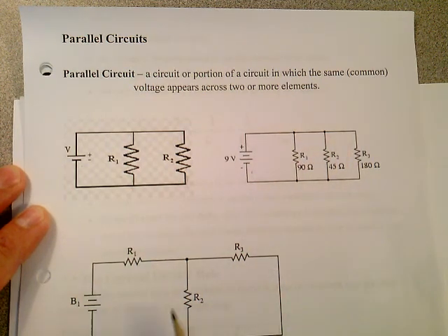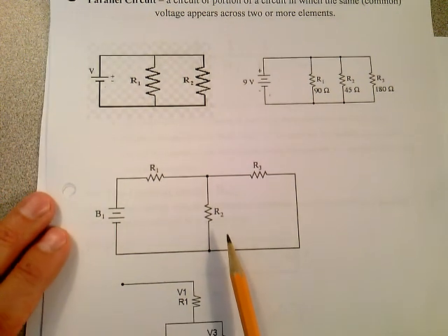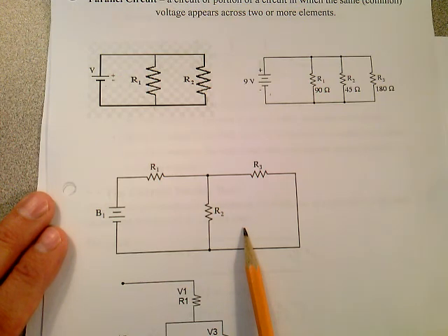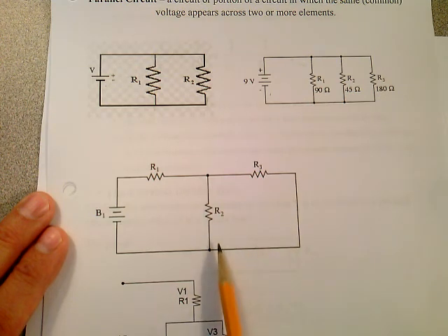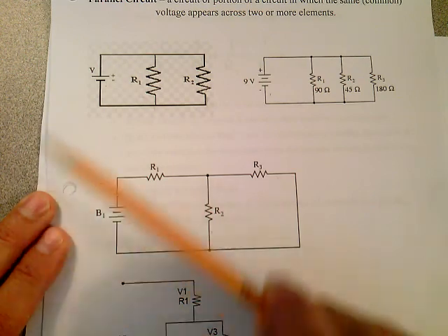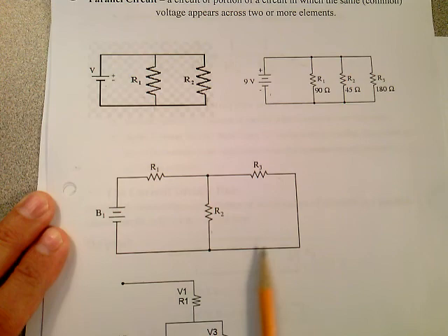Here's another example, but this is an example of a series parallel circuit. Take a look at this circuit. Do you see that in this circuit the resistance values R2 and R3 are in parallel? Don't let this fool you that this comes across horizontal here. This point is the same common point on both sides of the resistor, and this point is the same common point. This is all one point here. This resistor can be turned from horizontal position and moved down to the parallel position, and you'll get the look that you have up here.